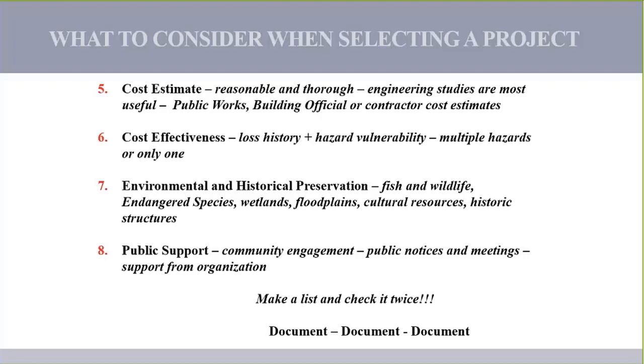Cost effectiveness is considering the loss history and the hazard vulnerability. Is it cost effective? Is it a small hazard that happens every 100 years? It may not be cost effective. Now, are you flooding every year and $5,000 is a big loss to a house worth $50,000? Then yeah, that's cost effective, but you will have to do a BCA through the FEMA software. But is it a cost effective project?